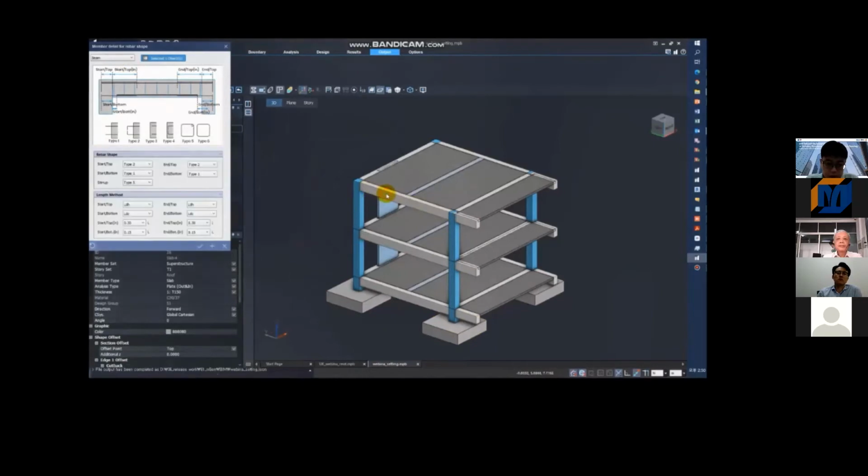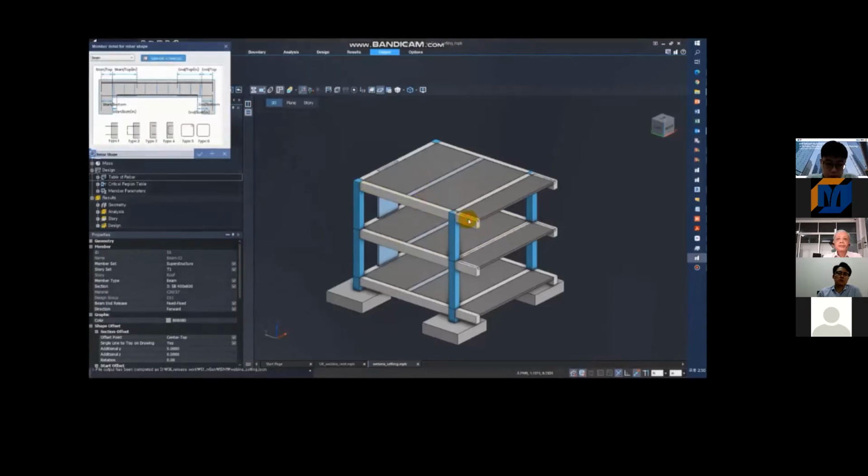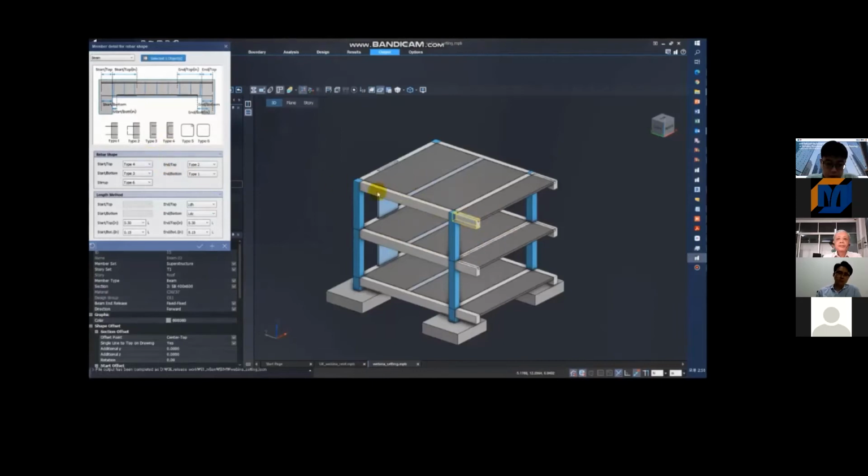Now let's set the shape of the rebar for each member. First of all, for the beam member, the top rebar at the end was assigned the shape of type 2, and the bottom was assigned the shape of type 1. The anchorage lengths can be assigned LDH, LDC, etc. according to each anchorage type. The rebar length at the end can also be selected as follows. In case of a cantilever beam, the end part is set to type 4.